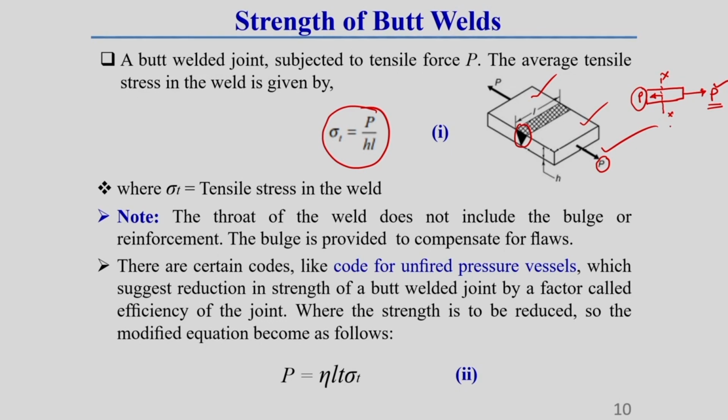So, what is called stress? The stress, if it is a normal stress, is represented by the symbol sigma. So, this stress sigma we can write as this resisting force divided by its cross sectional area. This cross sectional area is of what? It is the cross sectional area of this plane over which this resisting force is acting.